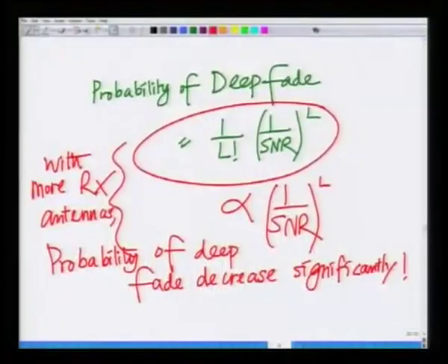And we saw the important reason here is essentially because we computed the probability of the multiple receive antenna channel being in deep fade, and we said that probability is 1 over SNR to the power of L. So, we said since the probability of the channel being in a deep fade is decreasing as we are adding multiple antennas, the bit error rate is correspondingly decreasing. And then we saw an intuitive reason for that, but I had to rush through it